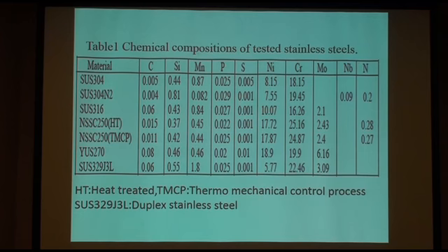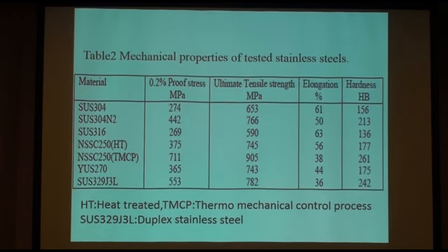So we tried to check these properties by use of ultrasonic fatigue testing, because we can get the giga-cycle data. We chose 304, high nitrogen 304, 316, and also 270. This is the corrosion resistant seawater stainless steel with 2.5 percent molybdenum, and 270 is one of the so-called super stainless steels. Their mechanical strengths are very high, in the range of almost 600 to 900 megapascals.